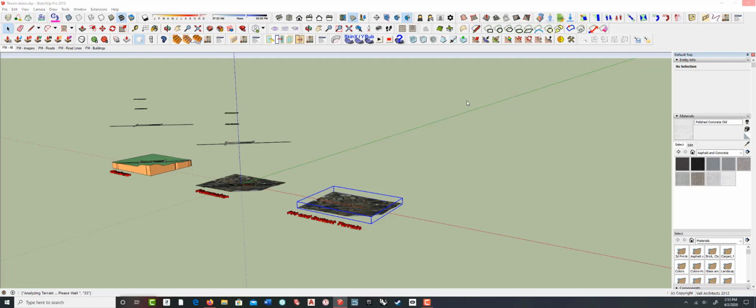So we have some guidelines. You don't really want to drape the geometry on initially because that splits the terrain mesh up into multiple pieces. And then when you start using the Artisan tool, the lines that aren't hidden kind of end up getting distorted. And also you get a lot of triangulation in the landform because it's been split up, especially in this case, I'm using a curvilinear form pattern, so it gets a lot of triangulation.